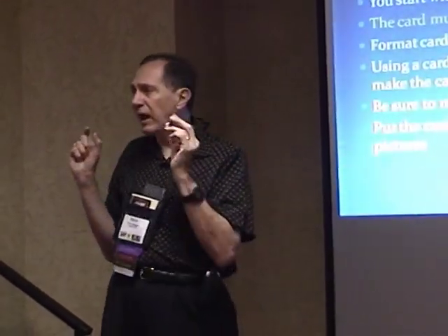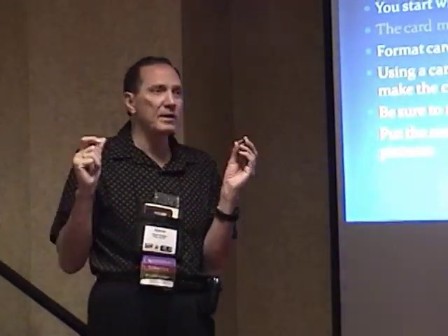Peter? Yeah, is there any extra complication if you have multiple cameras beyond just 2? If you have 4 or 5 cameras, and Bill Mull is building a 4-camera rig, it works exactly the same way. The only complication is this little battery pack that's supplying the power to do this. These cameras take about half a milliamp when that button is pressed. The little button cells, like the lithium coin cells, are only designed to output very low current levels. If you put 10 cameras together, there's not going to be enough current to drive all 10 cameras. You're going to need a much heftier battery. That's the only complication. Other than that, the software doesn't care.